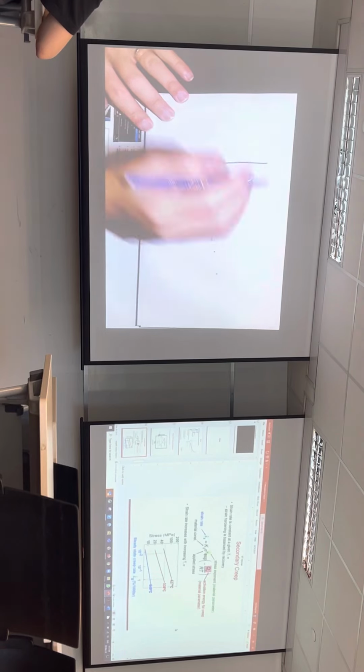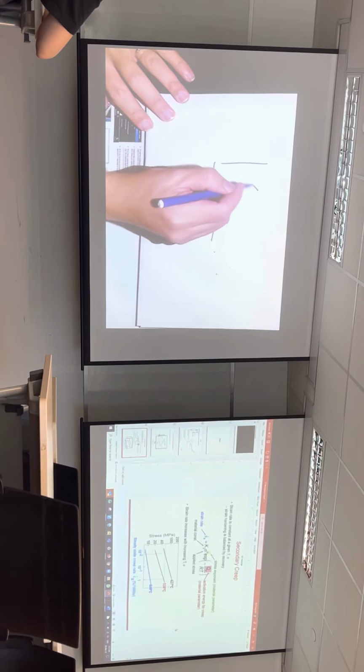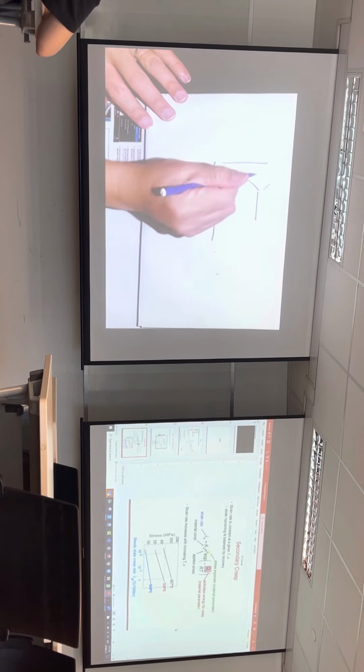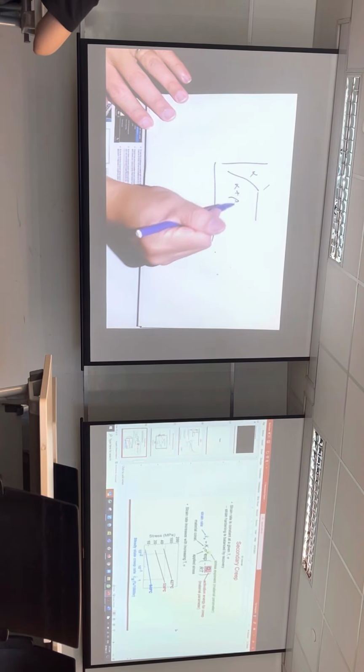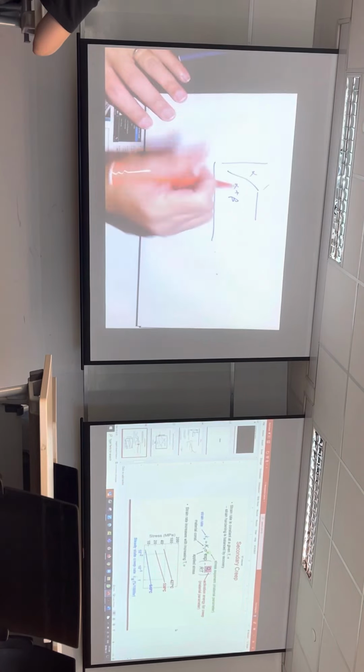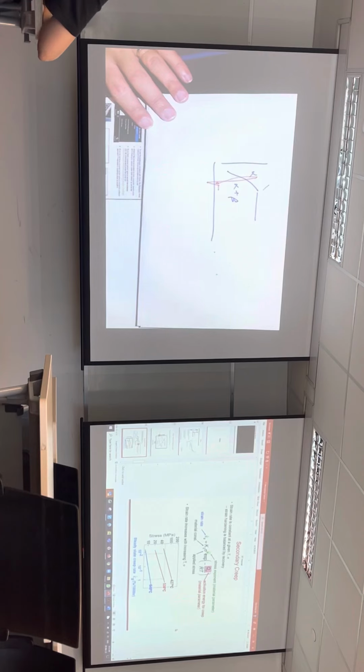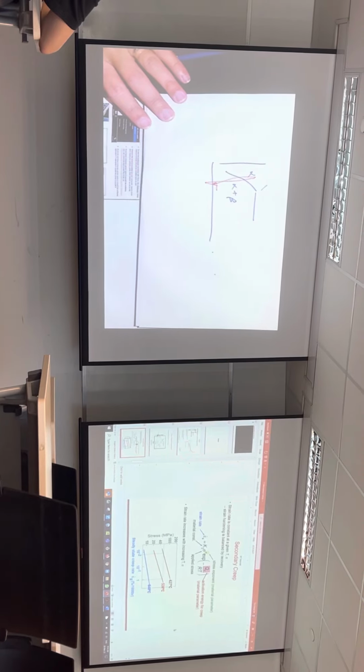For any kind of phase diagram, you expect this aging part. The aging part is the line forming precipitate. That's the hardening. Honestly, just write everything. The first thing that you always have to do is go to solution, come back, quench, then age. If you are here, only alpha plus beta already, you cannot age. It's like the icebox: it has to be frozen inside, meaning the precipitate has not come out yet.